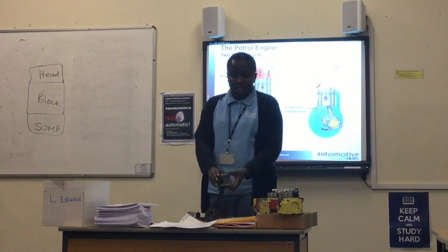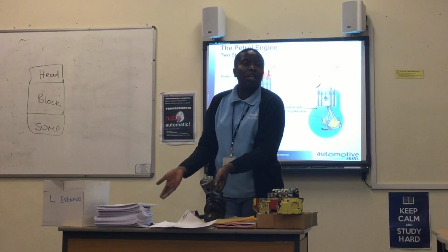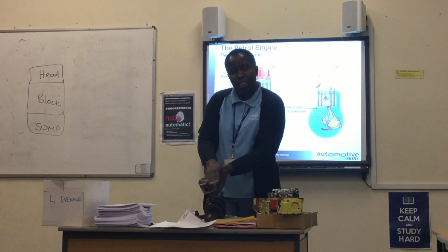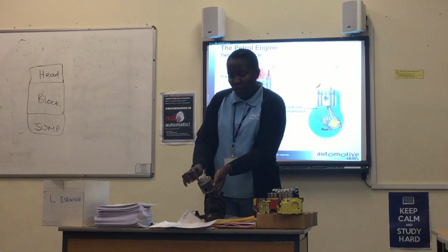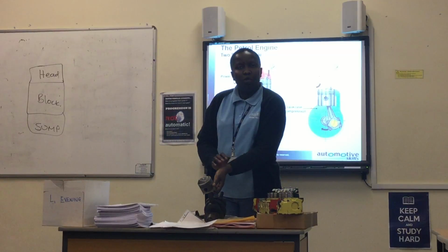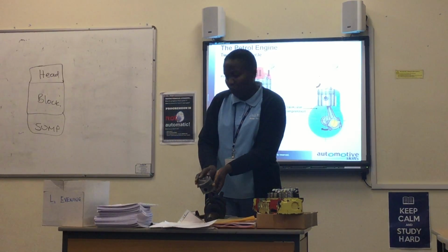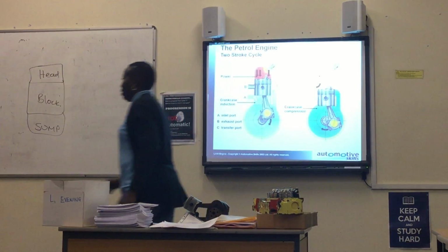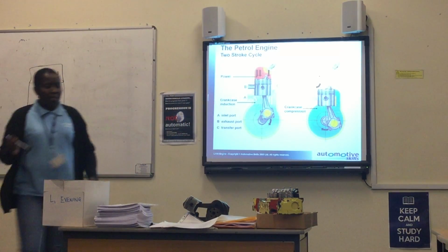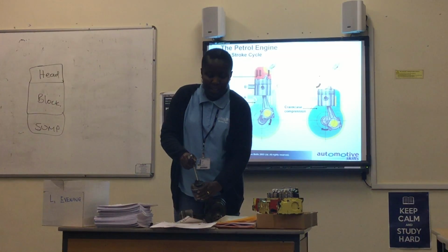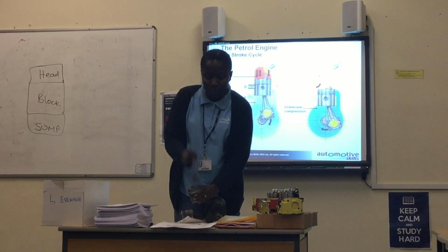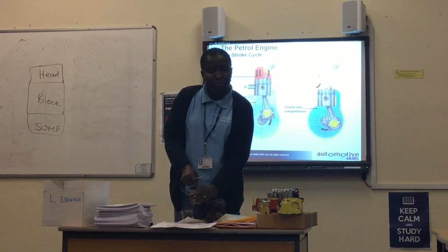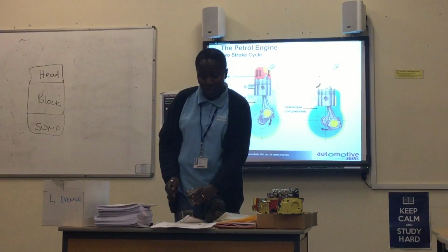Small engines have smaller pistons. And also the top of the piston varies according to the engines. Some pistons can have a flat crown. Then we have circles for valves, or we can call them valve recesses. So much so that when the valve is open, if we have a recess, the valve is not going to hit the top of the piston. So we'll be having some recesses at the top of the piston.